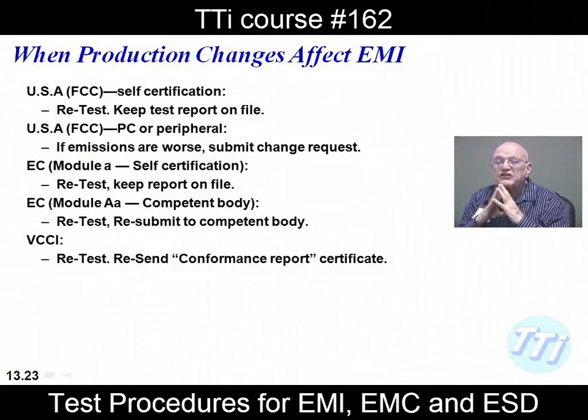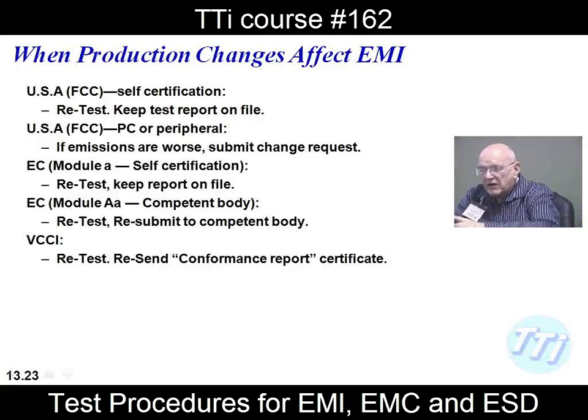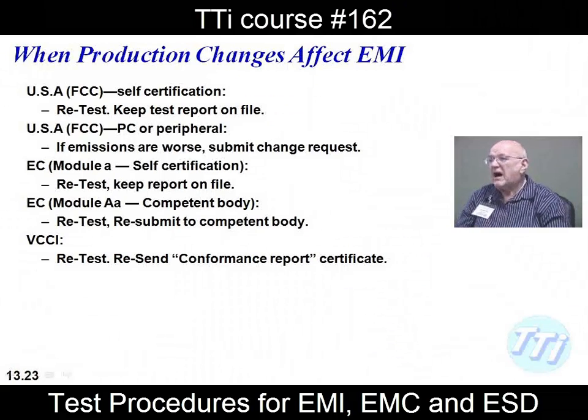When production changes affect EMI, guess what, guys? If you change the production method, you may have a part, item, or cable coming out of a different location. In the USA, FCC tends to be self-certification. So when you retest, you keep the test report on file.